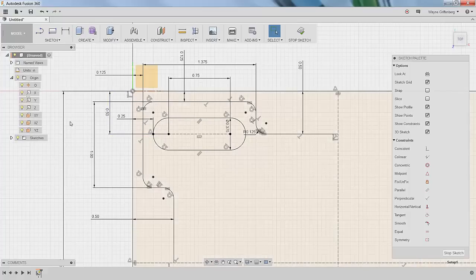Okay, so now all the blue lines, it does actually. Shift does work in Inventor as well, Dennis. You can use shift in a lot of those functions, but when you use it in dimension, you'll see if you hold shift, it'll also find the quadrants and the midpoints as well.